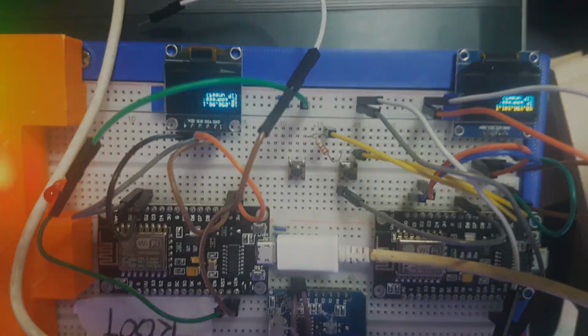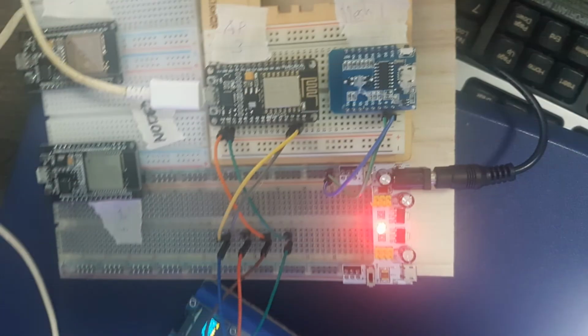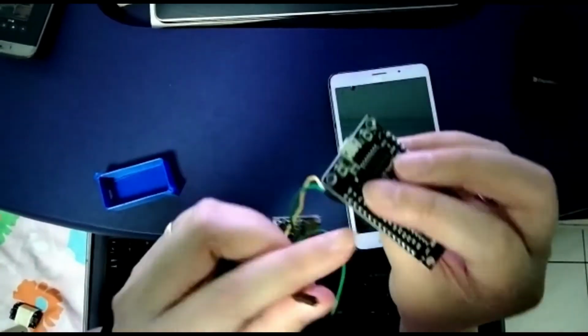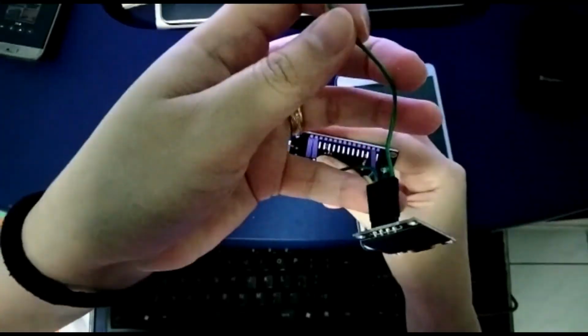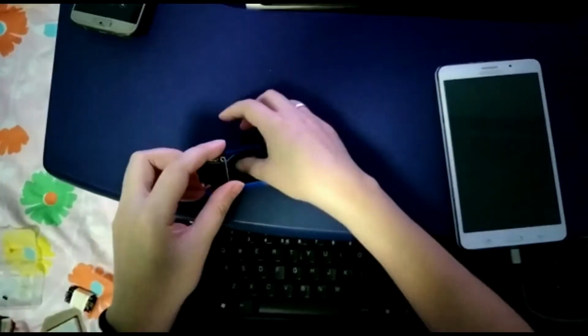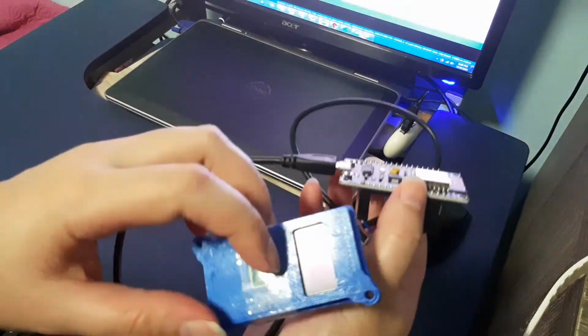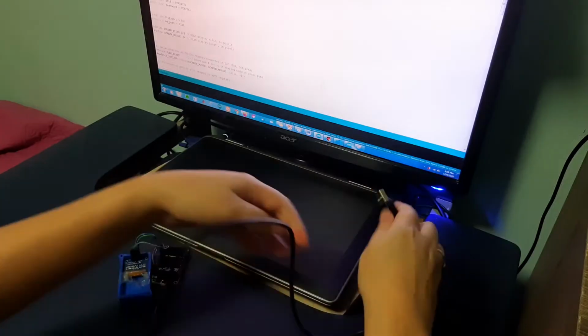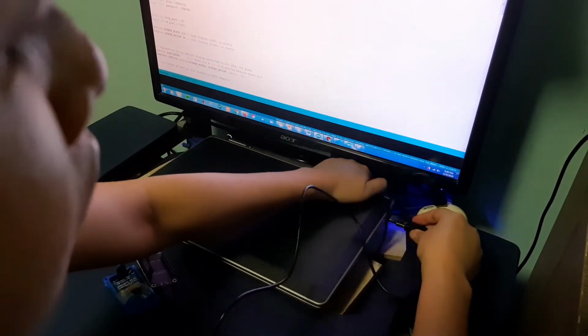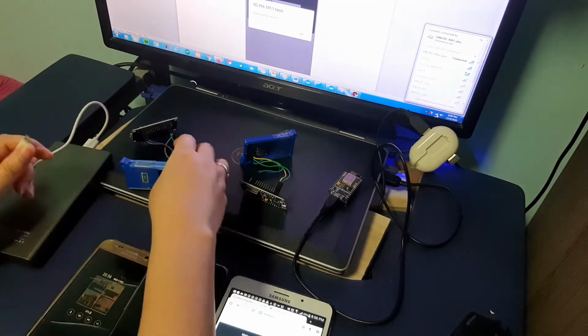I used a breadboard in the debugging stage. Now we can connect the OLED to the ESP pins using jumper wires. Check the pin connections, as a mistake will damage your ESP or OLED. By the way, we first need to connect the ESP to the PC USB port before we can upload the sketch. Plug it in and upload the sketch.